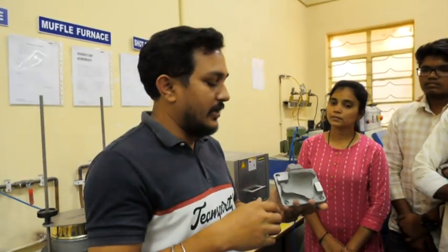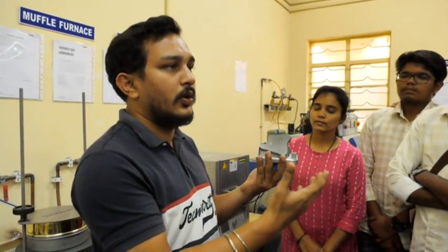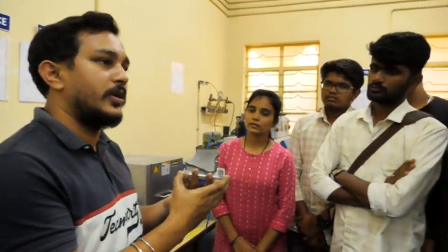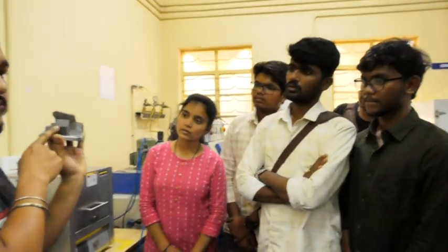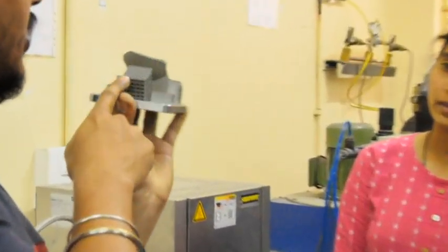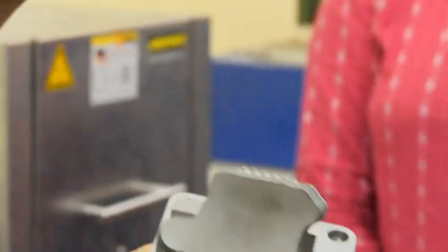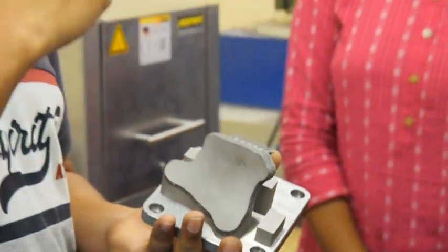Once it is printed, we will remove it from the build. Then the printed samples will look the same as whatever structure you give; that will depend. Here, if you can see, it was more than 45 degrees. This lattice, if you can see, they have given some support here. If you can visually see it, there is some solid support, right? That is in order to handle overhang structures.